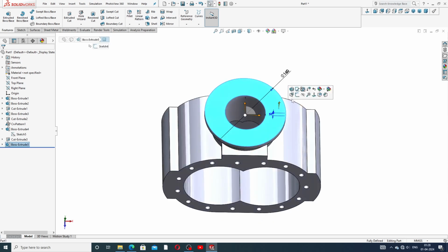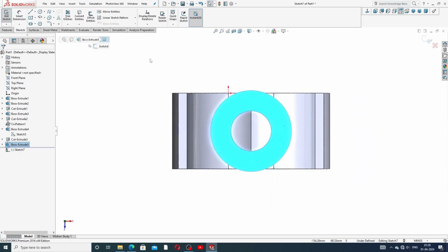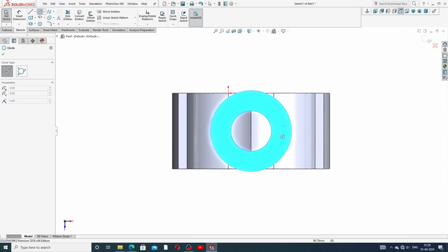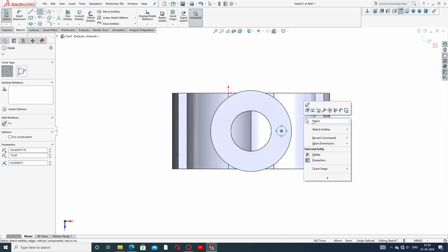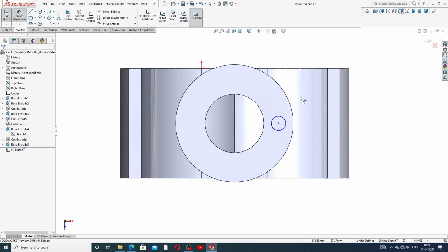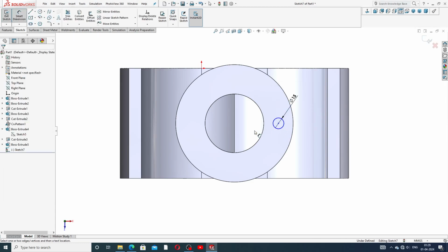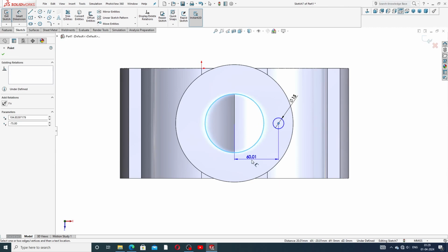And select this face, sketch, normal, and this hole is cut out, and this is a cutout, and distance between center to this point is 52 millimeter, and this is 15 millimeter diameter. Okay, and draw a circle. Circle is drawing here. Okay, this circle is drawing here, and this use 15 millimeter. Okay, and this point and this point is 52.